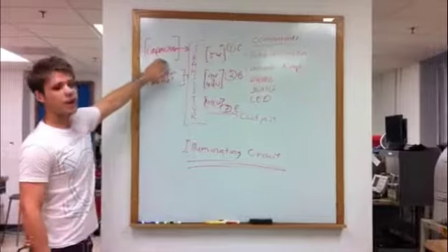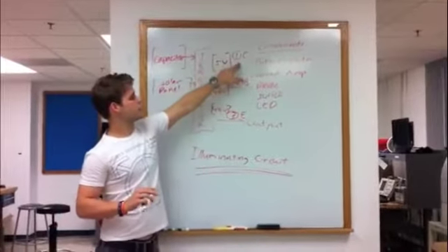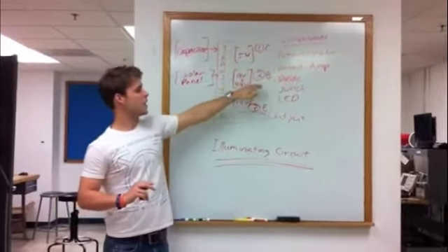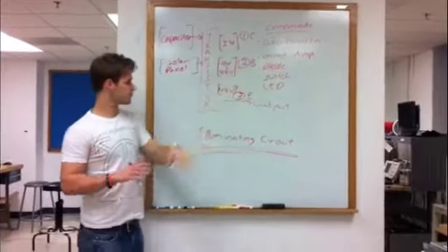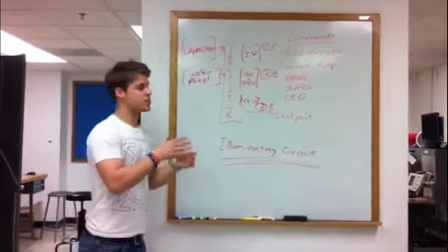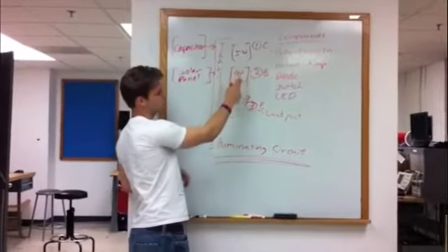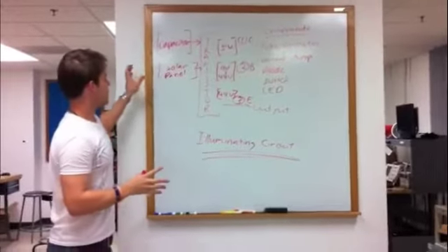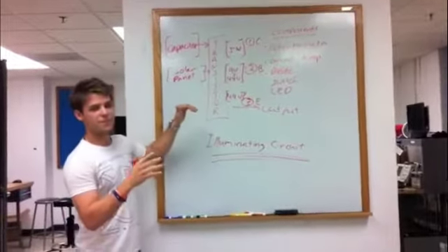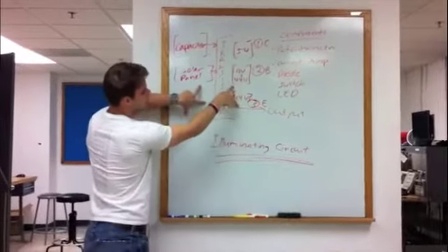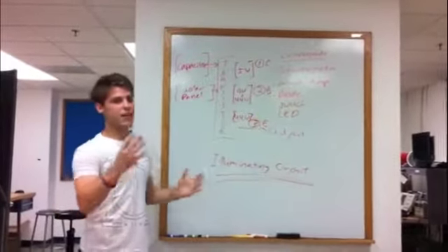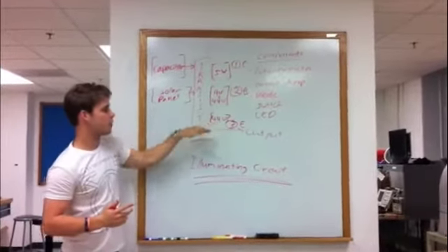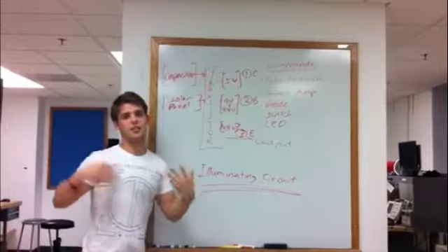So the idea is that we have the voltage of the capacitor at the collector pin of the transistor, and then we have the voltage of the solar panel flowing into the base pin of the transistor. What happens is that at nighttime, the solar panel is going to switch from 9 volts to 4.4 volts because of our resistor hooking up into the base. When that happens, the 9 volts drops to 4.4, and this says, hey, now the voltages here are equal, so let's let it flow. So at nighttime, we get these 5 volts to flow through and become, with the voltage drop, 4.4 volts going out into the LED and the charge monitoring circuit.